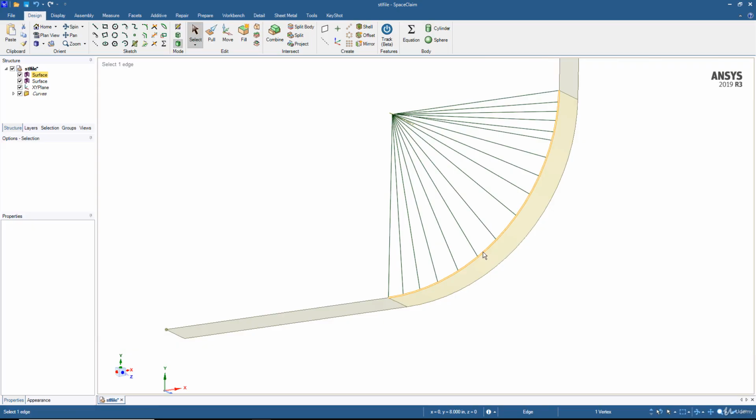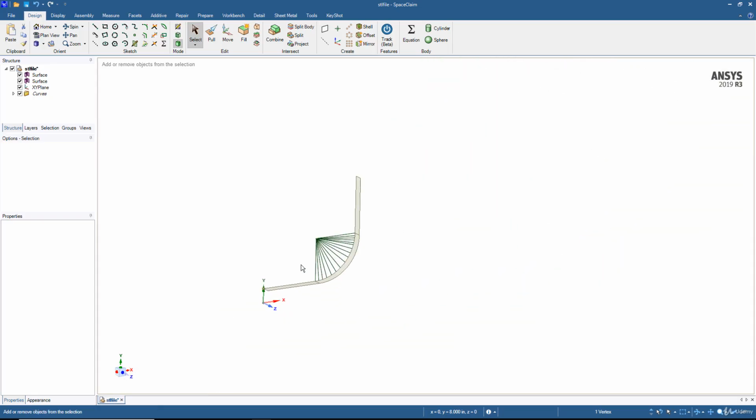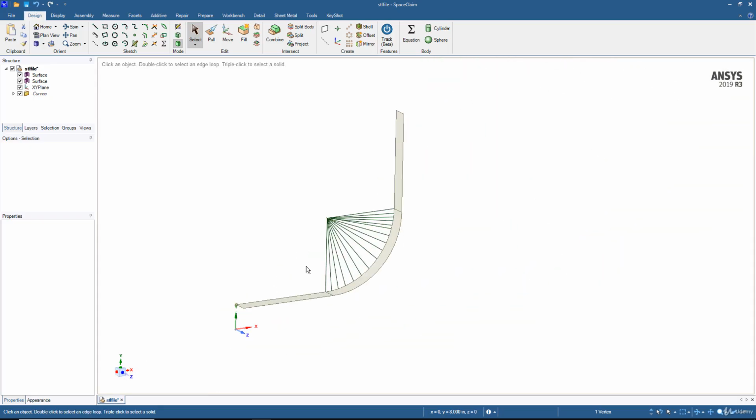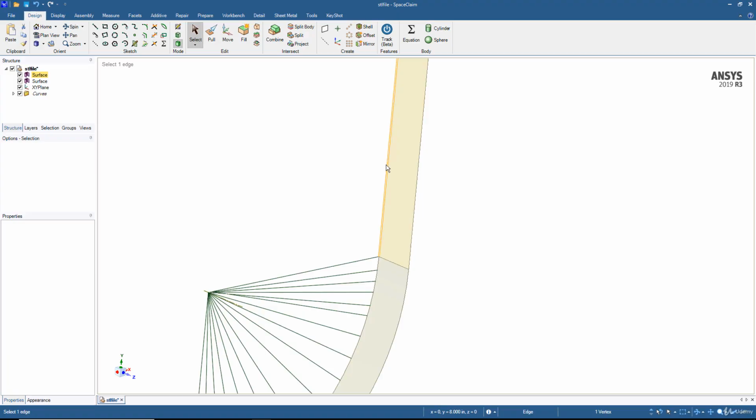And from the points, create the text file or the CSV file, and then import that file into CFD-Post, and this will create the line for this center line curve. And for this method, which is the current method here, I'm going to explain on the same geometry, which is the geometry of this